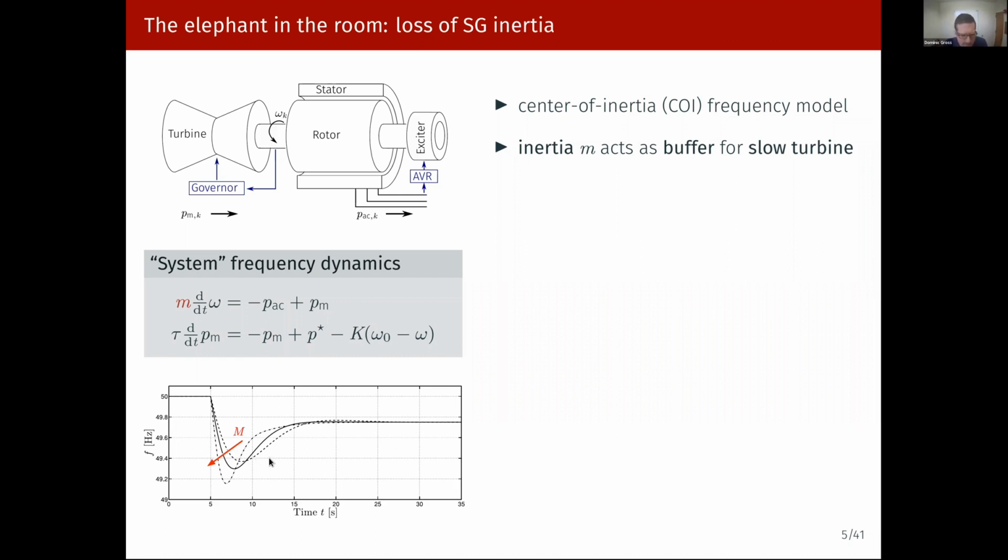problematic. And this has been basically a proxy for what happens if I take a power system as it is, I retire large-scale power stations with turbine governor systems and inertia, replace them by power converters that only have a constant power infeed, so they do maximum power point tracking, and I would crank up the governor gains of the remaining machines to keep the same frequency regulation. So this is where this curve here is coming from.